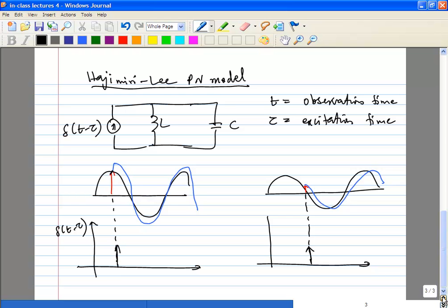But at the zero crossing point, I think the inductor current is not zero; energy is stored in the inductor. Yes, and that's why there is no DC shift. That's why there's no DC shift here, is what you're saying. Because the current is flowing through it, it just adds as charge to the capacitor. You're saying the current through the inductor cannot change suddenly. Yeah, that is definitely another way to look at it.